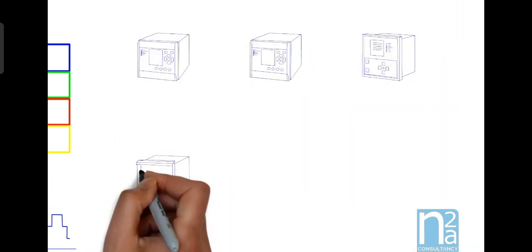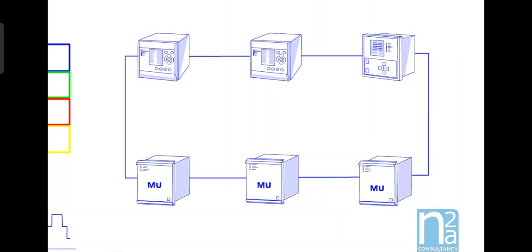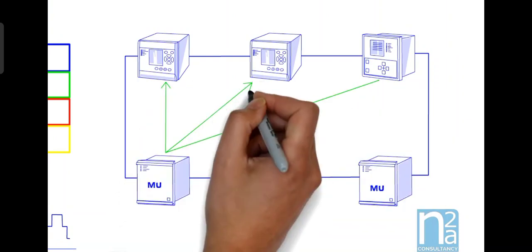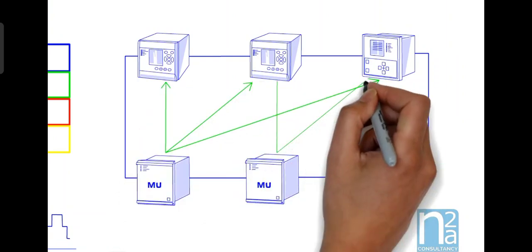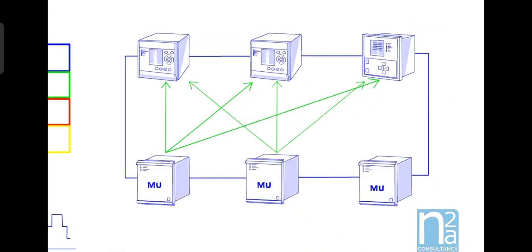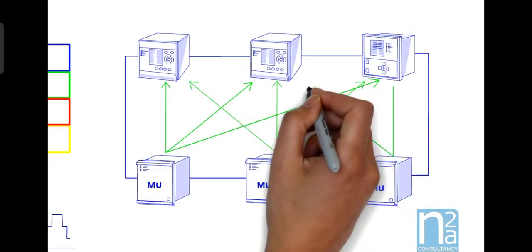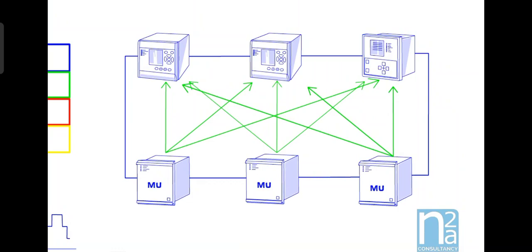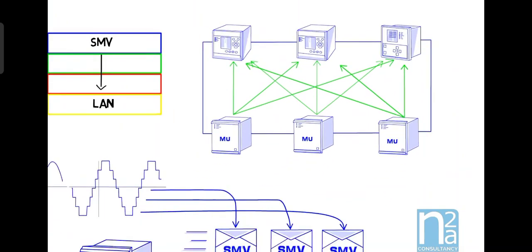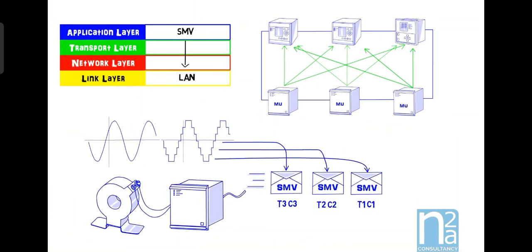And this without additional wiring, just by using the process bus, which needs to have a sufficient bandwidth to support this large flow of information. In medium voltage application, because of physical proximity between the relay and the switchgear, it is not much used today. But the possibility to share values of voltage and current, and the absence of copper wires in the medium voltage compartment, could be an advantage.